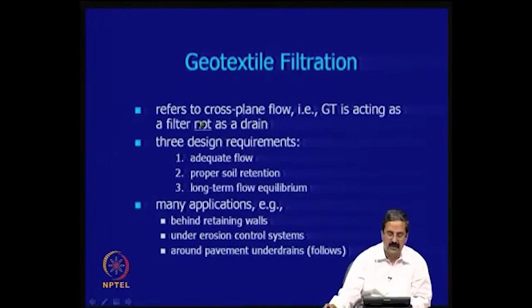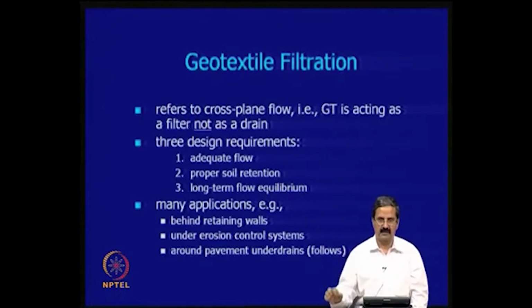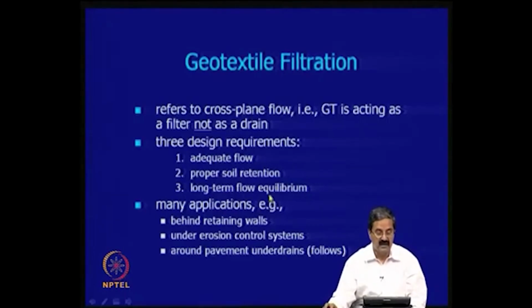So, geotextile filtration refers to the cross plane flow, and the design requirements are that there should be adequate flow, proper soil retention, so you should be able to retain the soil, and also long term flow equilibrium. You should be able to filter for a very long time, say 20 years, 10 years, 5 years, whatever, because it is not easy. This is a very important concept, particularly what happens in the long term.